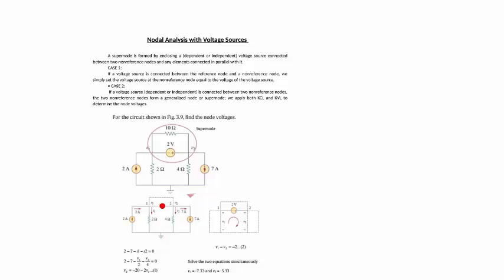What I mean is, generally when you look at it from here, I do I1, I2, I3, I4, and I5, I6. These are two separate nodes. But once I take this voltage source out, I will look at these two nodes as one, meaning whatever current is entering here and here, I'll add those two.